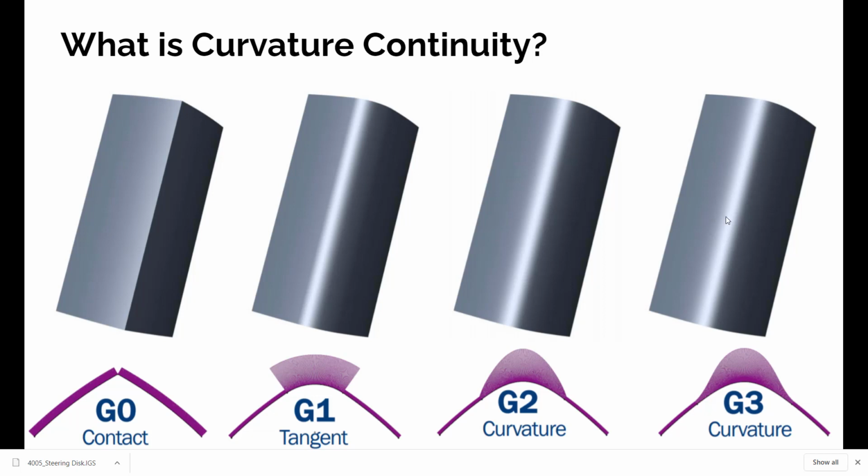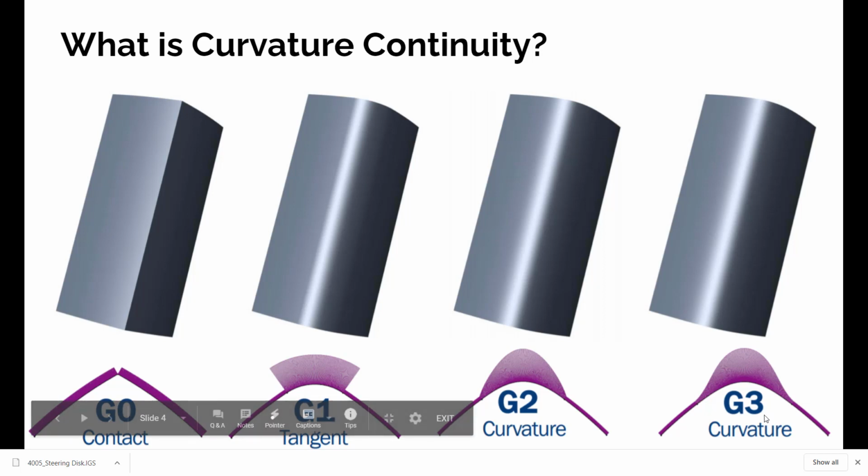This one, typically, you're only going to get inside of your sketch. That's why I want you to use splines, because especially the style spline is great at giving me G3 curves in a surface.